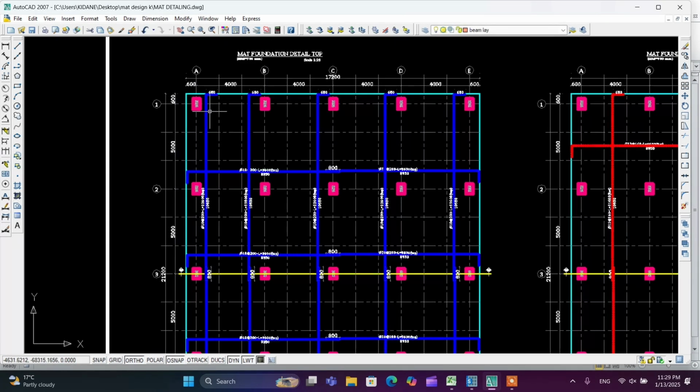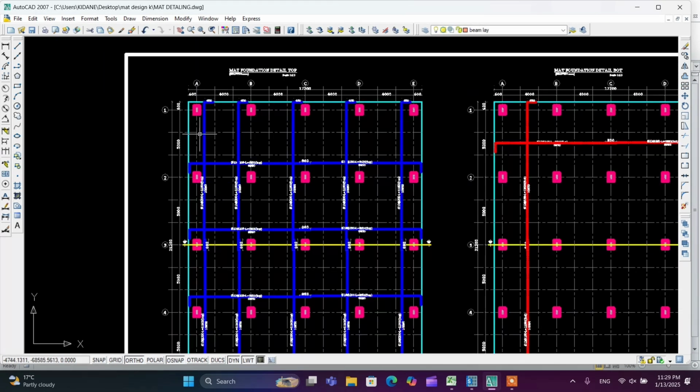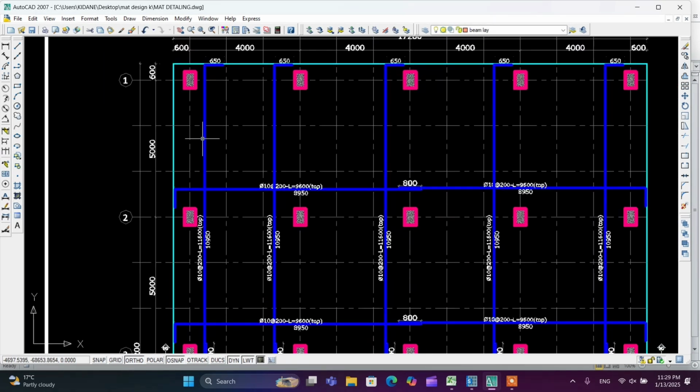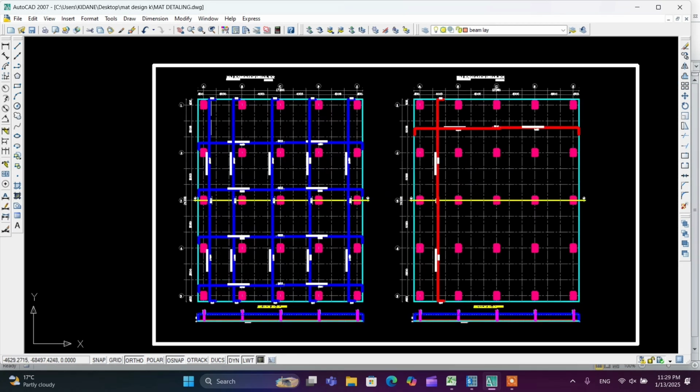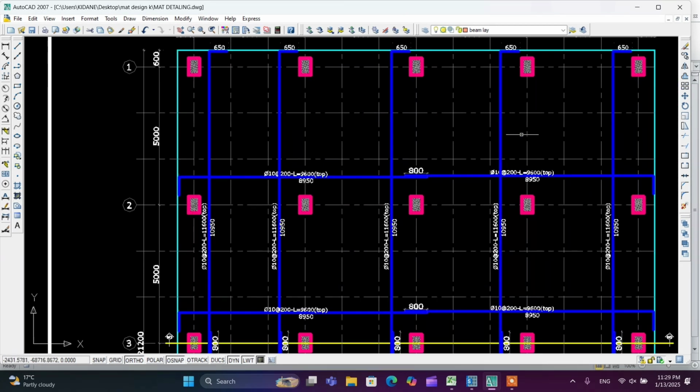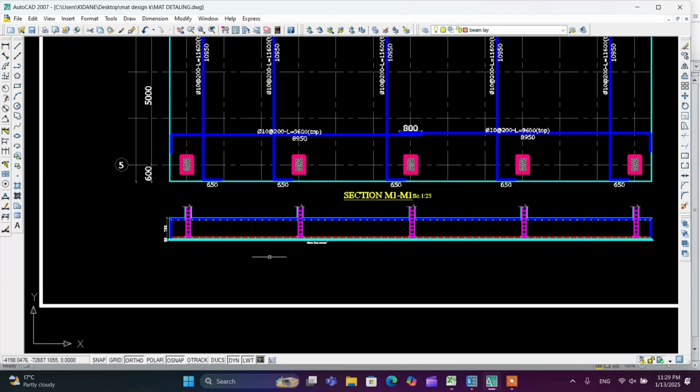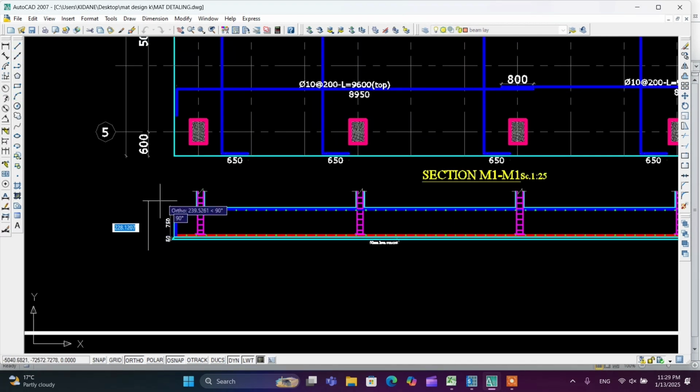So the additional reinforcement for the top one is put around the mid span. This is because our moment looks like this. I will show it. So at the support, our moment is maximum around here and becomes, I will draw it.